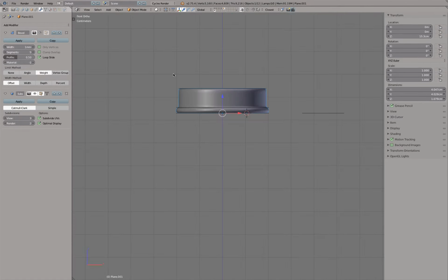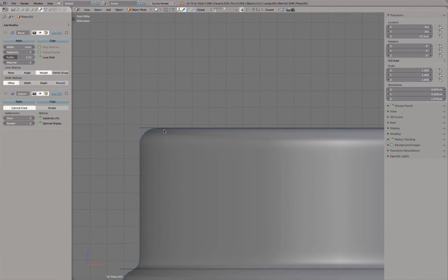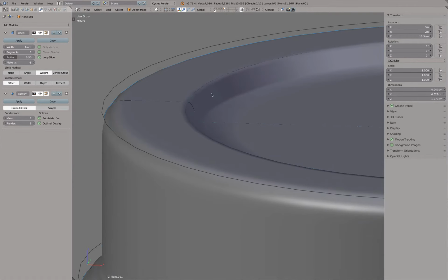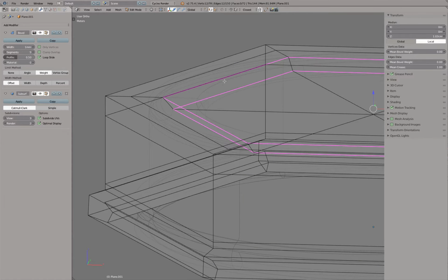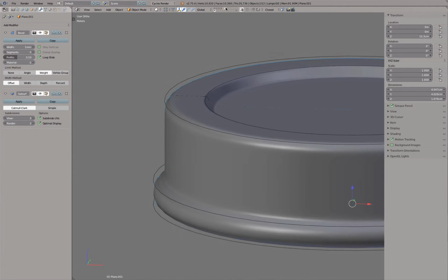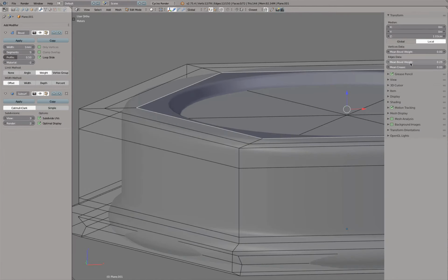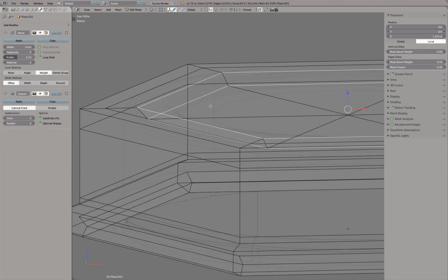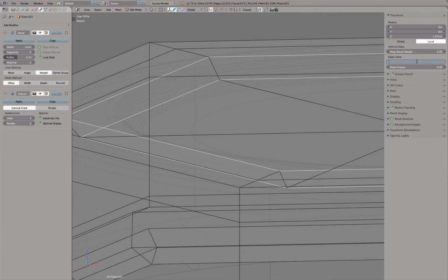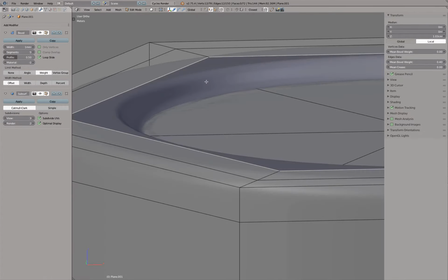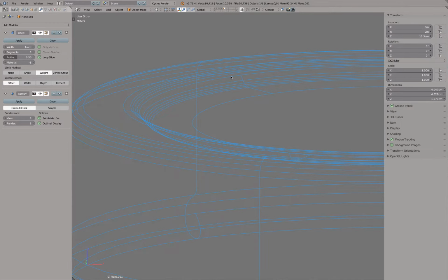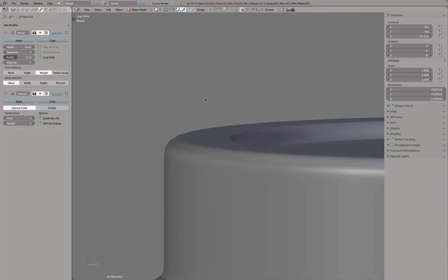Perfect. Okay, so we can turn this one back on. So we see, for example, this edge. And up here, I'm going to be lazy. I'm going to simply crease this maybe with a 2/4 value. So like 0.25 millimeters edge rounding. And that seems to be pretty okay. And let's say maybe 0.5, how does it look? Yeah, 0.5 is getting too big. Parts are intersecting. But actually with a 0.4, that seems to work out pretty well.